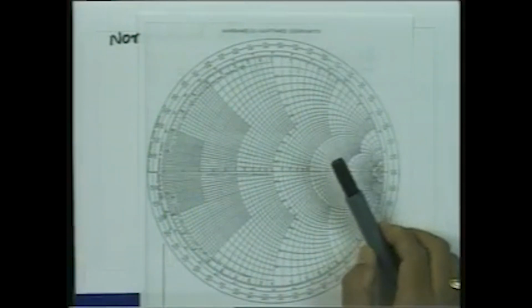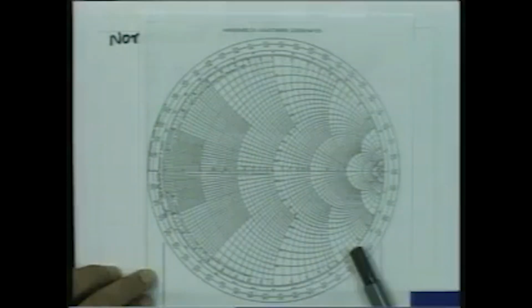So, any normalized value of r, which is equal to the same normalized value g, will represent the same circle. So, as long as we are dealing with normalized quantities, the impedance and admittance can be treated in exactly the same way on the Smith chart. However, the normalized values of g and r, or b and x, have different meanings physically.